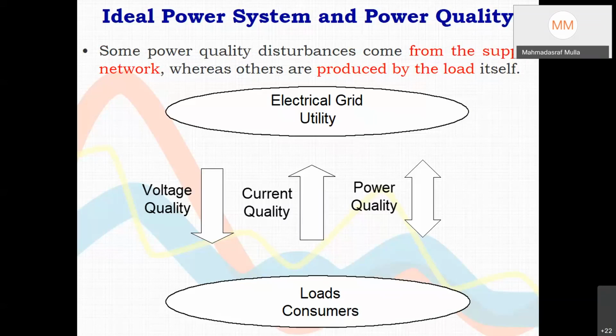So what the other sir commented is right. The utility's job is to provide one fixed magnitude voltage to all the loads, irrespective of how many loads are connected to that transformer. That voltage should be of pure sine nature. And on the load side, we will have to assure that all the loads draw a pure sine current. When any load is drawing pure sine current in phase with voltage, we can say the equivalent is like a resistance. So the utility would like to see all the loads as resistive loads.